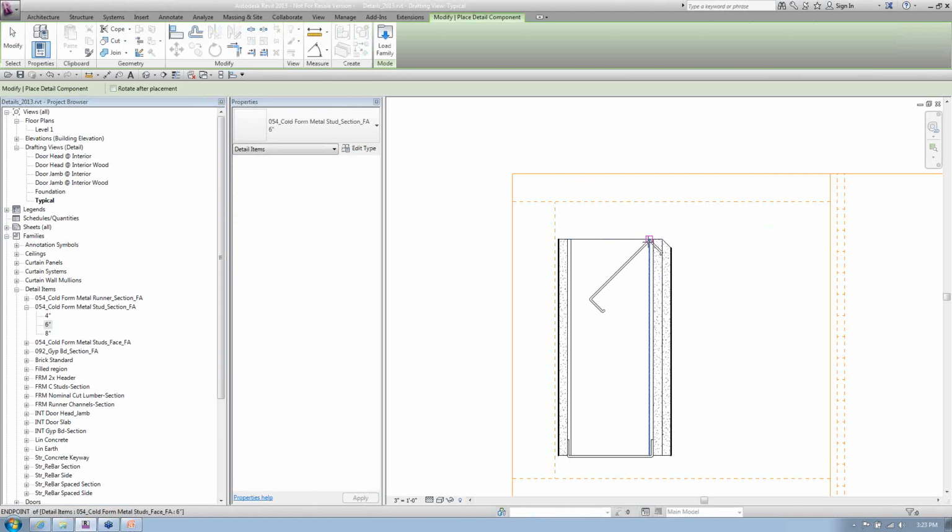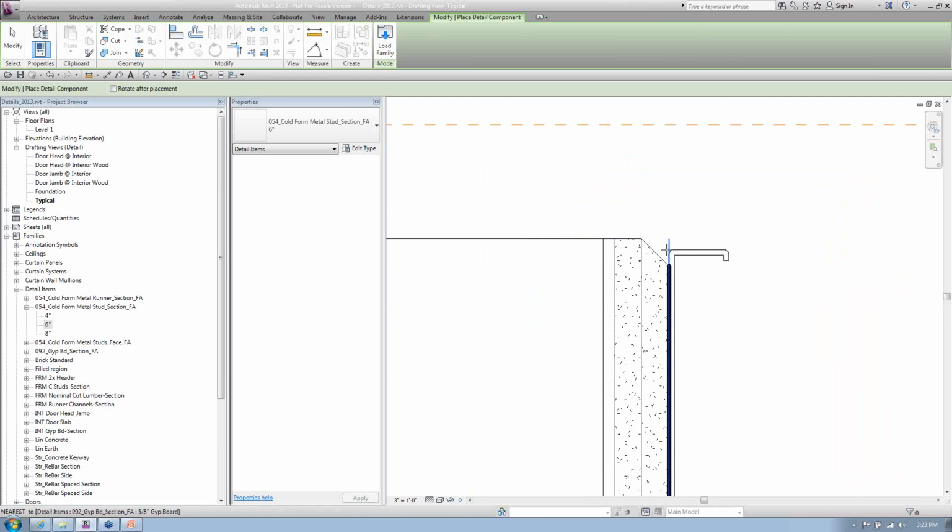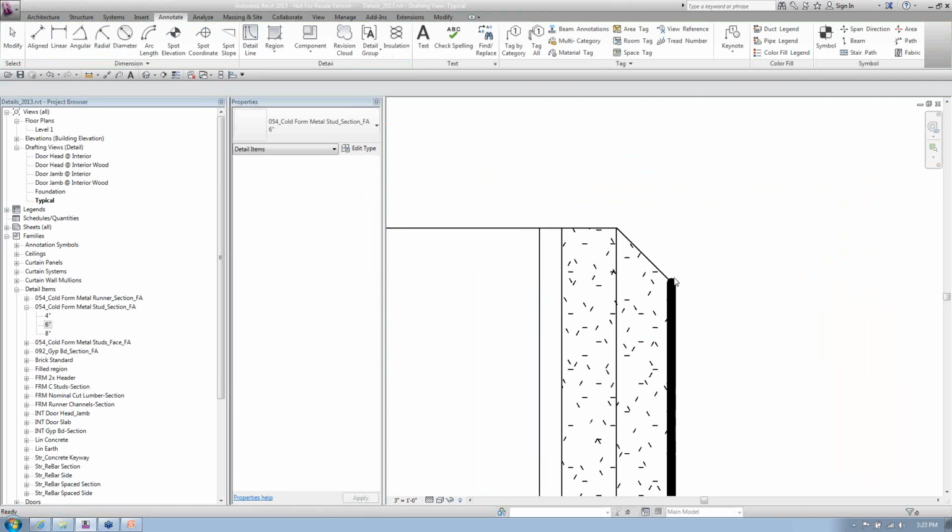If you wanted to have something coming off a wall at a 45 or something, you don't have to place the component and come back and hit rotate. You just have to get to an intersection where you can then hit the spacebar and go at 45 increments. Now, what if I'm dealing with something that isn't at 45 or 90 degrees? Then you've got to use the rotate command. Yeah. So unless that's also the fact that if I come over here and let me change something here real quick to answer that question.